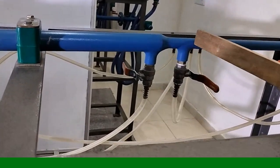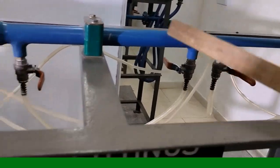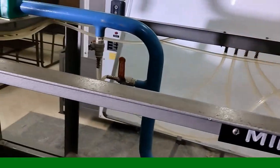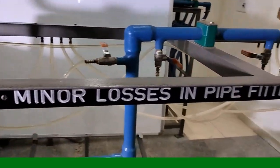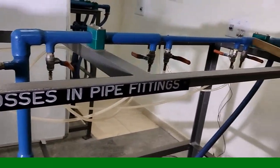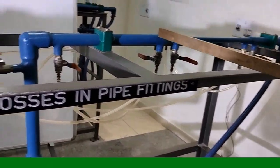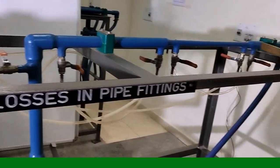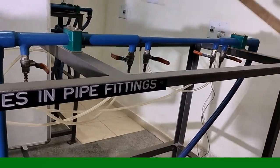Now, first we have to decide which experiment we are going to do, whether the sudden contraction, the sudden expansion or the bend. Suppose we are planning to conduct the sudden contraction experiment. Make sure that all these pressure tappings are in the closed position.